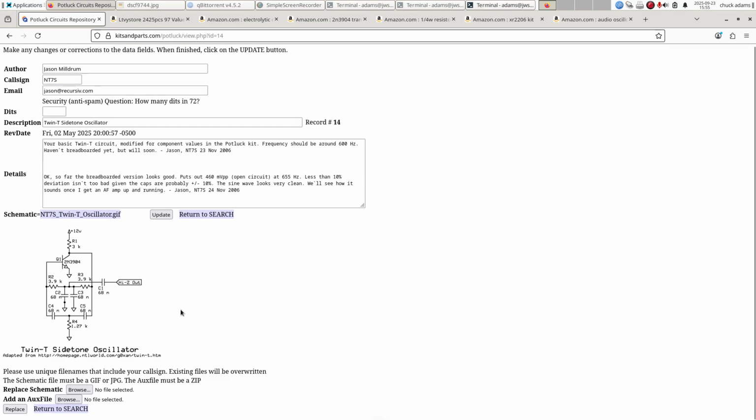If you build this thing, and I built one, it didn't oscillate until I added a 100 nanofarad monolithic cap from B plus to ground. I may have even put it on the collector, but I don't have this critter anymore, and I'm sorry, I love the word critter. I'll build one because we can use it for this project, but I'm going to give you another alternative.